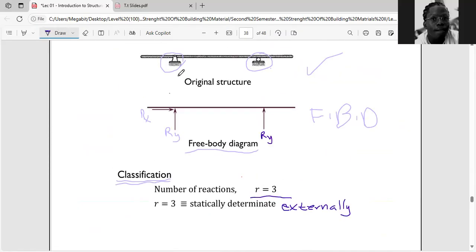That is all you must know. As I told you earlier, my best advice is to try as much as possible not to forget your number of supports. The three basic types of supports we looked at are the roller, the fixed, and the hinge. For the roller, we have different types. You may meet a roller, a rocker, or a link support in the question, but you should always know that those kinds of support have only one reaction. That is your key. But if you identify that it is a hinge support, then you have to remember that it has two reactions.